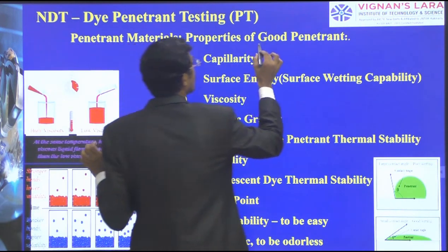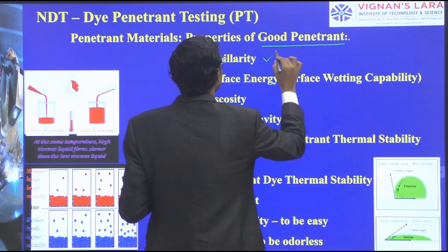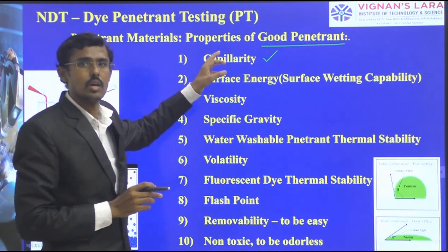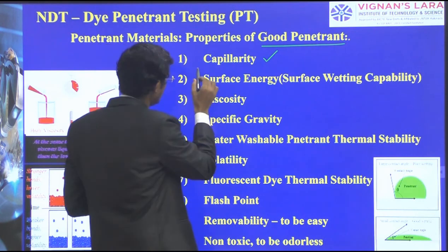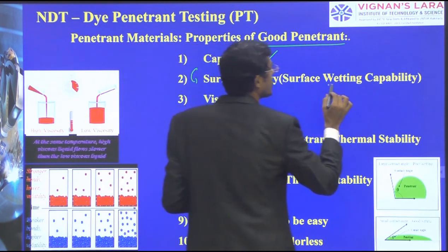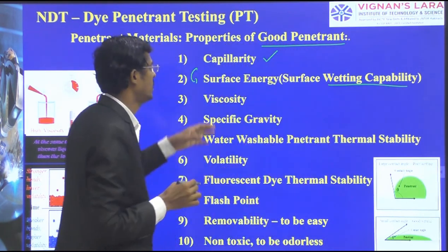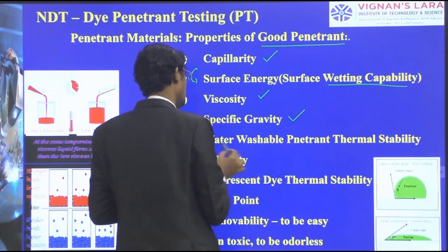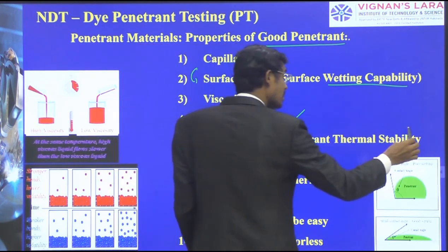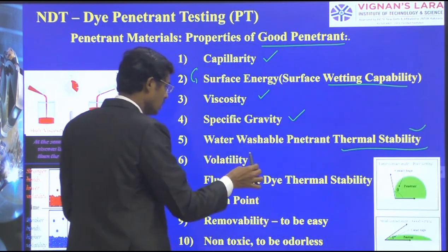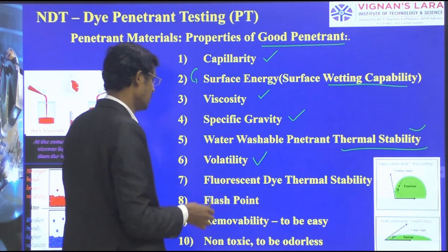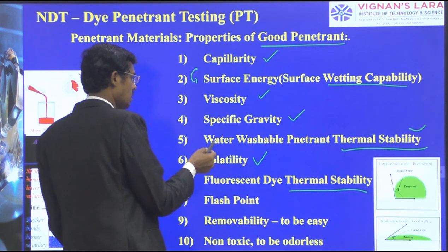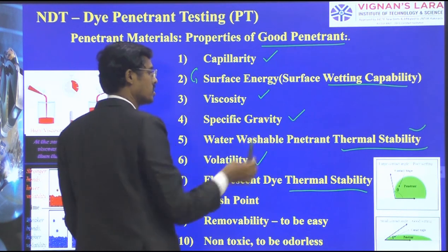A good penetrant should have good capillarity force, surface energies involved there. That is nothing but surface energy, surface wetting capability. And then the viscosity, one by one we will see viscosity, specific gravity, water washable penetrant thermal stability, volatility, fluorescent dye thermal stability.